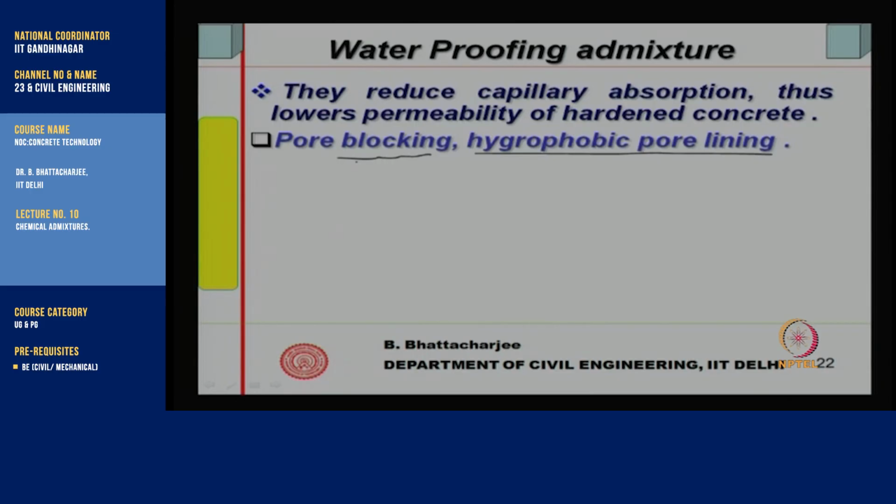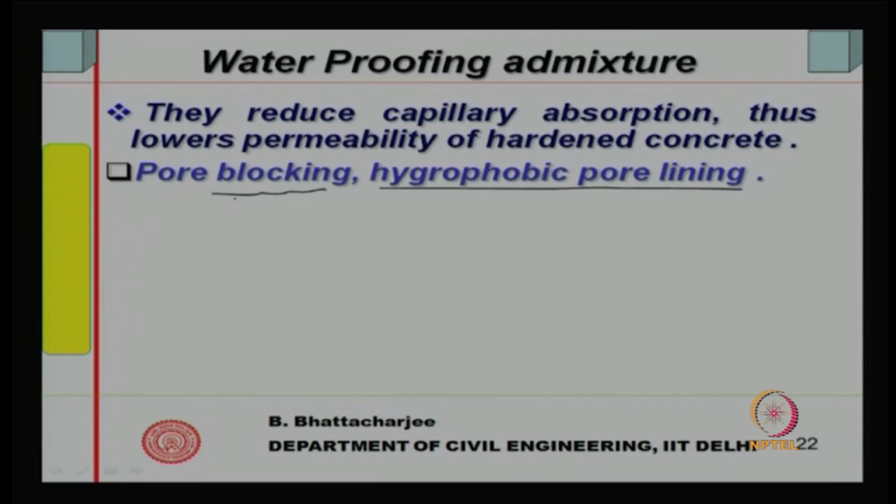Now, hydrophobic property is essentially because of the contact angle between this material and water. For water and normal surfaces of concrete or many other things, glass let us say, the contact angle is 0. So, water is a wetting liquid for this kind of material. Surface tension properties, I think we discussed sometime, or we may be discussing later on. Let us quickly have a look at this. It will be something like this.